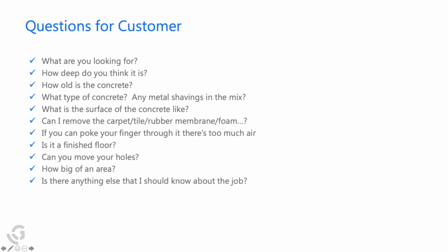What are you looking for and how deep is it? This will help you to determine which equipment set to use. How old is the concrete? This will help with dielectric, giving you more accurate depth readings. What type of concrete is it? Are there any metal shavings in the mix?